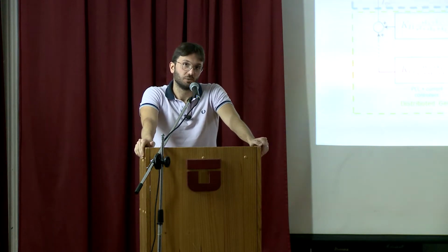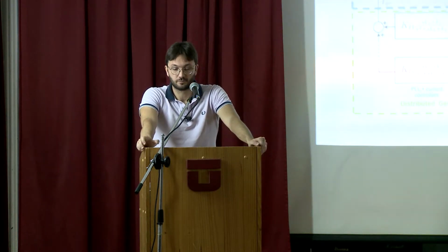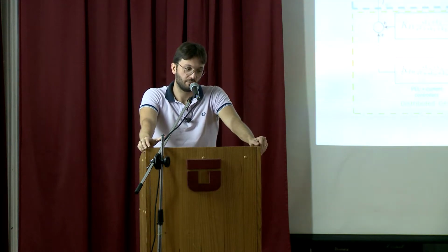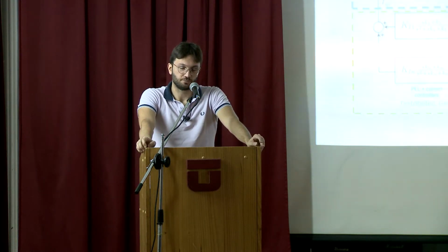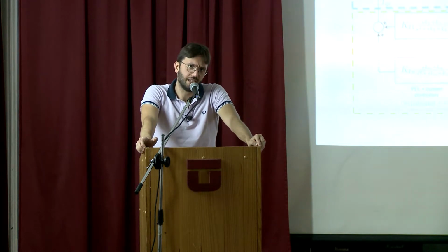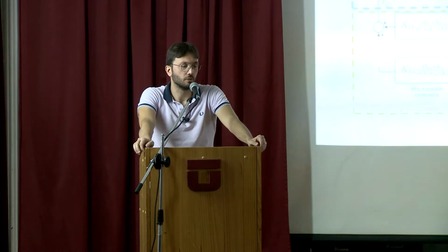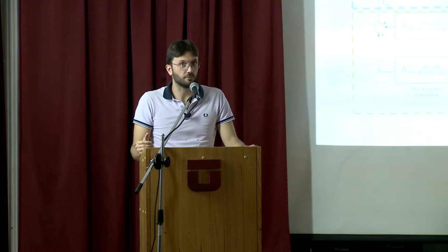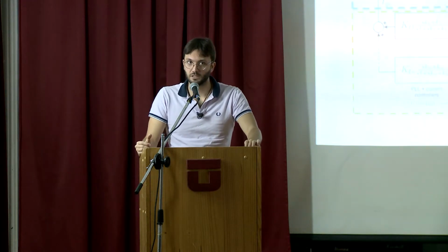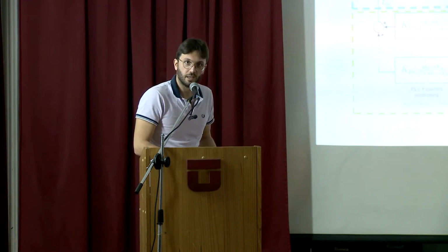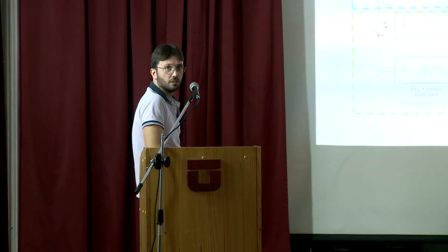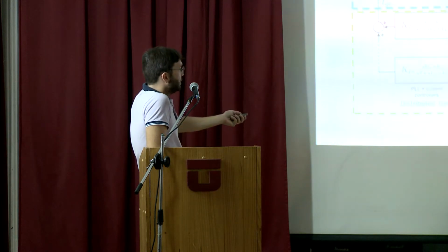We have to analyze with transfer functions what is happening. Of course, the system is nonlinear, the PLL is nonlinear, there can be many aspects, so this is just, let's say, an approximation. However, considering the dynamics that we are considering with some big DC-link capacitor, from what you have seen, the simplified analysis was matching very well the actual experiment. So we have a requirement basically on the bandwidth of the PLL.